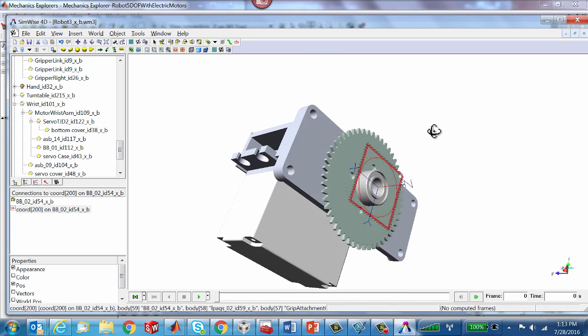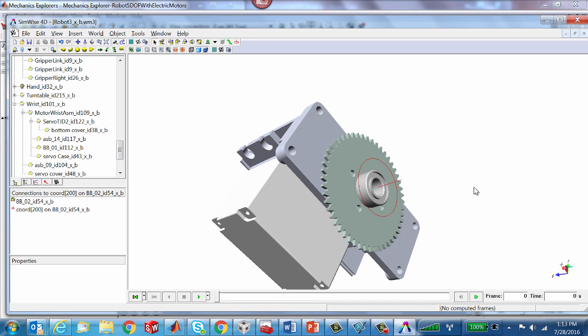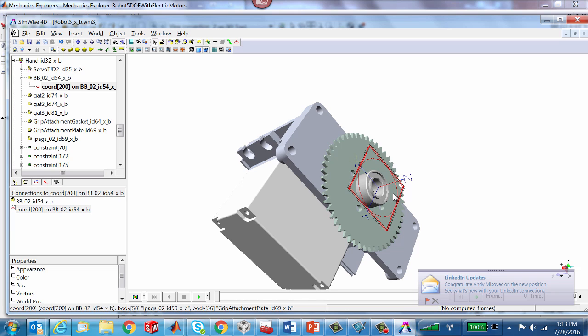When I place a frame, it always has a z-axis pointing out. And actually, if you look at its non-selected state, this idea of a frame kind of looks like a thumbtack. And if it's a thumbtack, the pointer of the thumbtack is going to be your z-axis, right? And it's a little bit tricky to explain why this is so important, but I am going to make reference to the idea that the most common method of defining orientation is what they call Euler XYZ orientation definition.